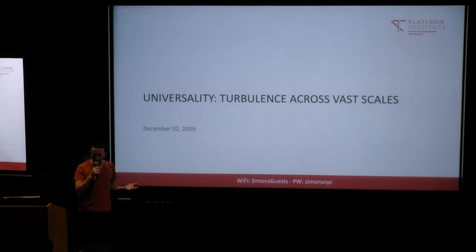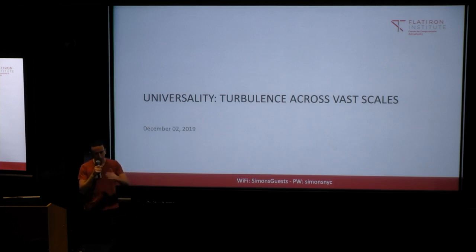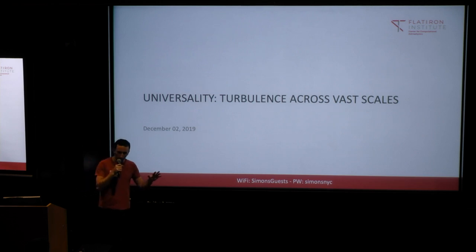And the poster that I'm presenting is proposing a scaling for curved shear flows, a scaling that would cross over from the purely inertial scaling that has been known since Taylor at the beginning of the 20th century, to the purely elastic limit. It provides a proposal for how to go from one limit to the other, and how to reconcile the fact that elasticity alone in the purely elastic limit can drive the instabilities, or can also be stabilizing in the more inertial limits.